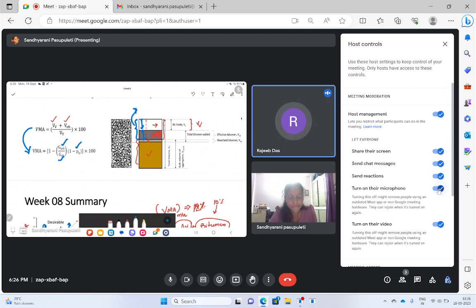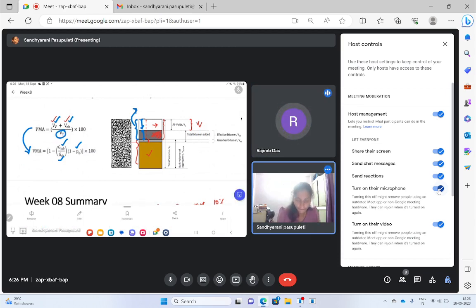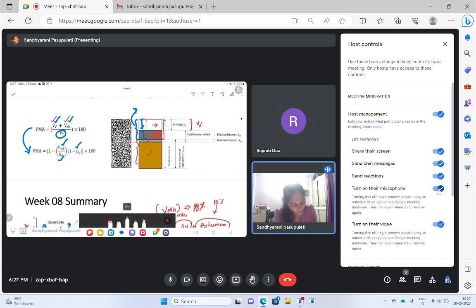But here for VMA you have written volume of voids. Acha, volume of voids. Correct. So yes, ma'am. Volume of voids plus volume of effective bitumen out of total volume. So we should maintain that VMA. VT is total volume of the specimen. Yeah, total volume. So out of this total volume, we should have this much VMA.